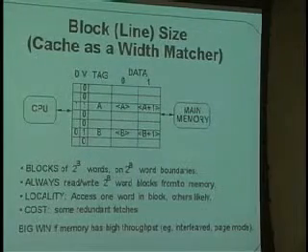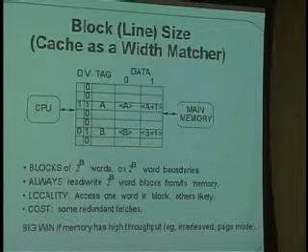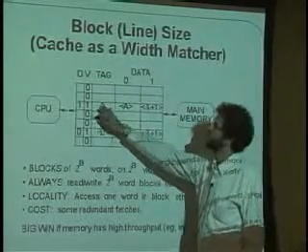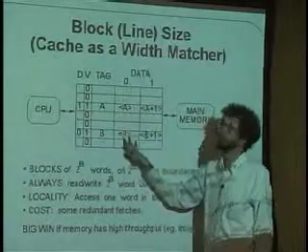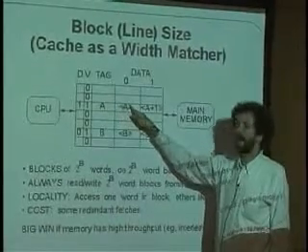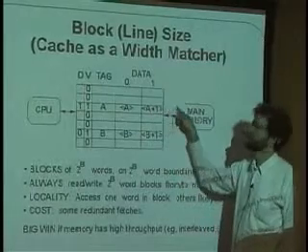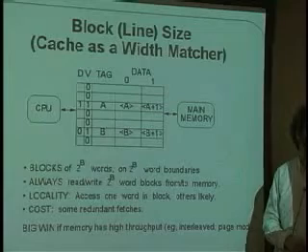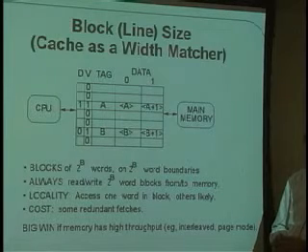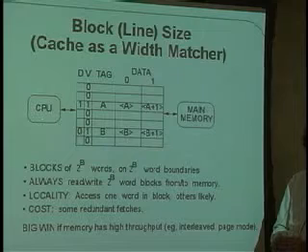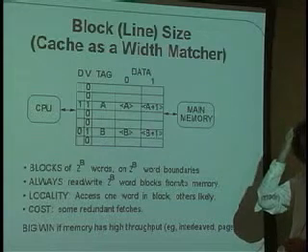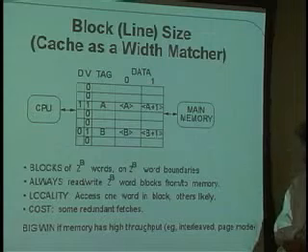Often because of spatial locality, when we bring in one item from the cache, we want to bring in the items that are near it. And the way that this is done in cache systems is that associated with a particular tag and the valid bit and the dirty bit are not one word of data, but several words of data. Here is the data at address A, here's the data at the next place and the next place and the next place, however large the block is. Typically, this block can be anywhere from 2 words up to usually less than 100 words, but a fairly large block. In general, whenever we bring anything into the cache, we bring in things that are near it, because we bring in the whole block.